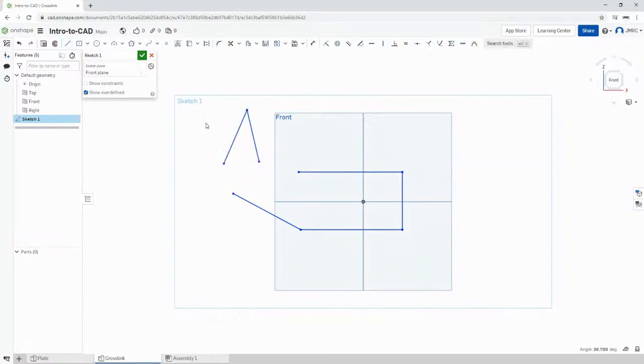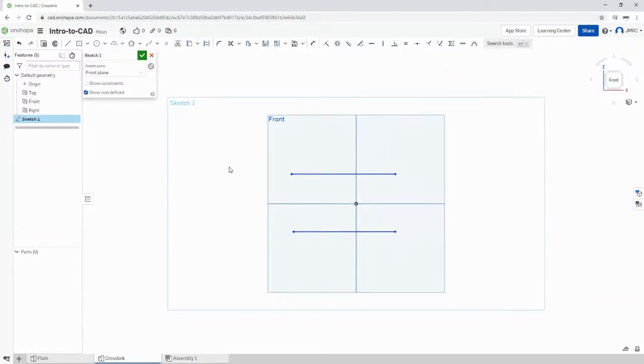Another tip, I'm going to create a window selection, deleting these lines and this line. Next, I prefer creating an arc. Also, we can create a circle. So I'm going to head up, selecting a 3-point arc. Take note of the shortcut key for that. Arc tool active. Let me place our first point here. Left click on this endpoint.